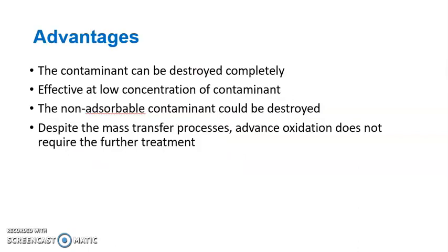So as I mentioned, there are several advantages in applying the advanced oxidation processes. First, the contaminant can be destroyed completely. No further secondary treatment is required. We don't need to deal with the disposal of the residual.